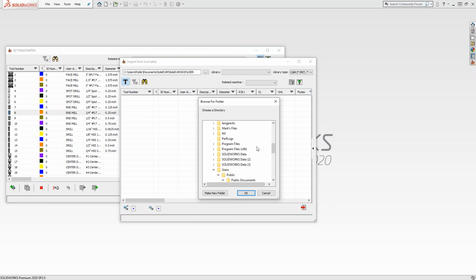Yeah, no, that makes sense, and that's why I was saying a better procedure would be, just like Kevin said, get those dimensions and make it globally to start. So get the dimensions, close out of the file, and do the global definition of that holder, so it's always global, rather than trying to go from local to global. That's a general thing for all tool table functionality. It's usually better to do it globally, and then it exists for all part files.